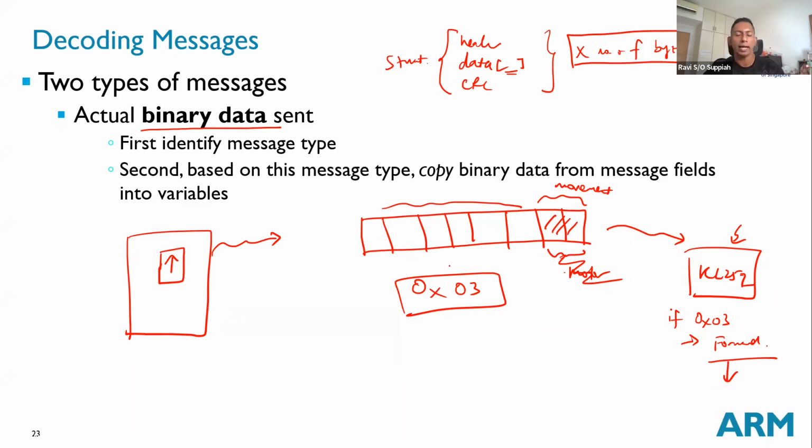You can say that I decide everything in the app and just send everything over in the byte. So maybe 2 bits for movement, 2 bits for LED, 2 bits for audio, and things like that. So that's up to you. You can say that the app will send a particular data packet and I will just extract it and use that to control all the subsystems in the KL25Z.